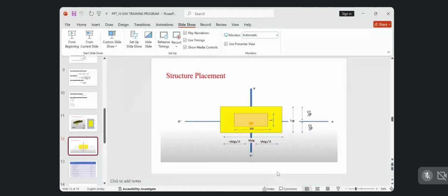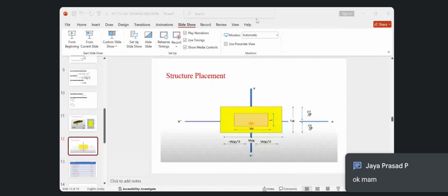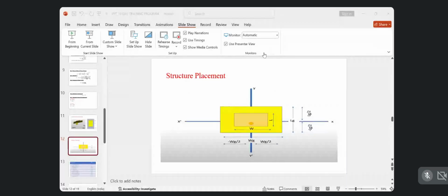So we'll start designing it. If you have CST Microwave Studio, kindly start the design with me. We have to go to new template, microwaves, RF or optical, choose antennas, click next. We are going to design a patch antenna, so choose planar and then click next.